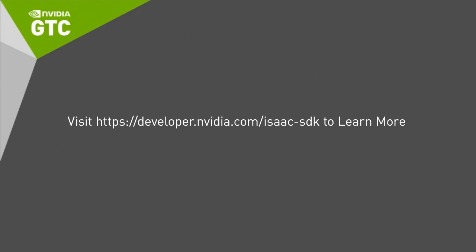Another question is, will it have the sim to real features to transfer to the real robot? As Hamad said, we have domain randomizations, which help your algorithms be much more robust by randomizing the looks and the physics properties as well, so that when you transfer to the real robot, reality is just another randomization from the algorithm point of view.